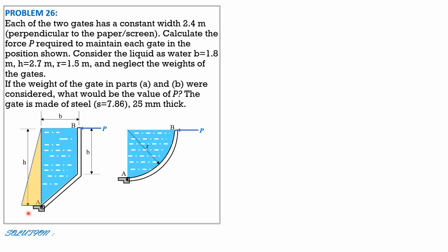the hatch gate. So this is gamma of water times H, pressure here, and the distance of F, which is horizontal, is H over 3 from the bottom. Because the pressure distribution is triangular, this is exposed to the atmosphere. Let's divide this trapezoidal section into two parts, rectangular and triangular, as shown, so that we can compute the weight of water on this rectangular part. Let's call that WR. Its distance from the vertical line through A is half of B, of course. And we have W triangle. This is B over 3.